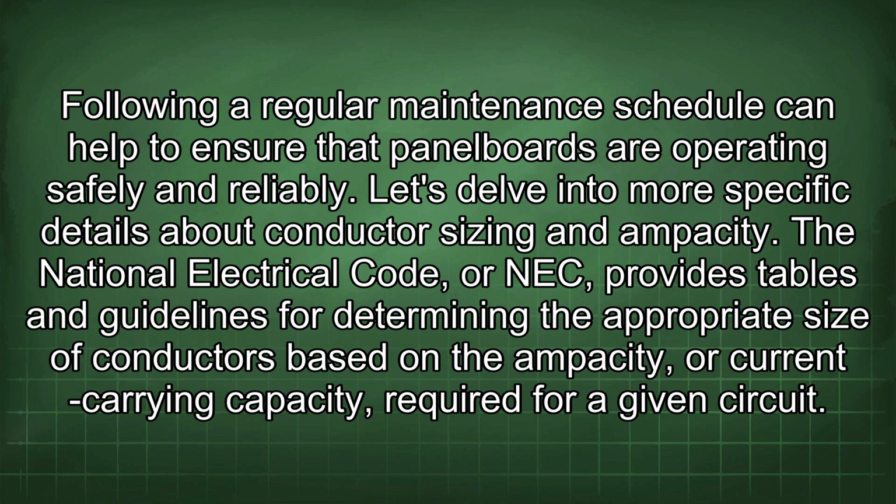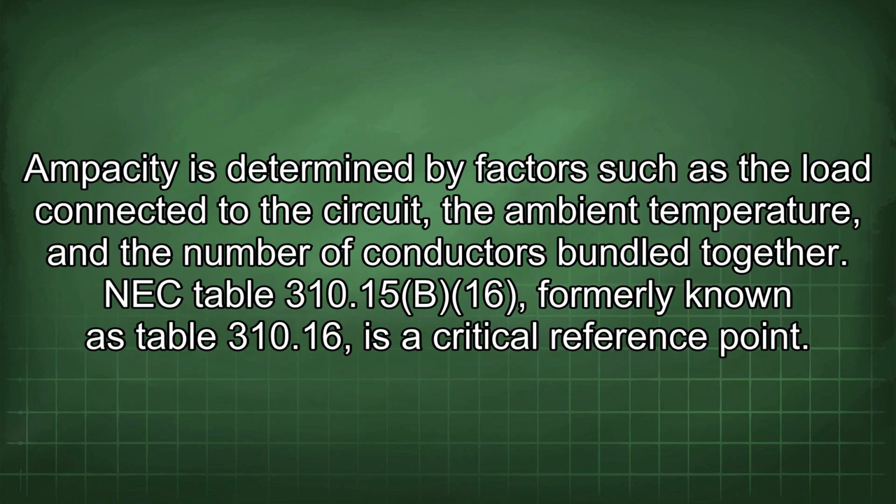Let's delve into more specific details about conductor sizing and ampacity. The National Electrical Code, or NEC, provides tables and guidelines for determining the appropriate size of conductors based on the ampacity, or current carrying capacity, required for a given circuit. Ampacity is determined by factors such as the load connected to the circuit, the ambient temperature, and the number of conductors bundled together.